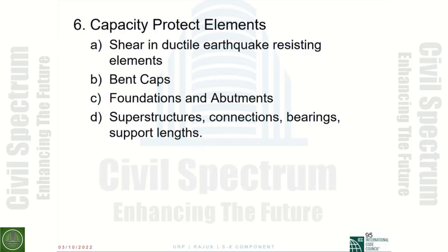The main specs, which is the LRFD design specification, will give you a force-based approach. You will have an R factor there. You will have values for the R factor. You will have values for the yielding element where the R factor is more than 1. For the protected element, you have the R factor equal to 1 or actually less than 1. That will become an amplification factor.